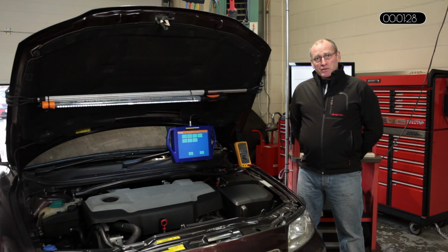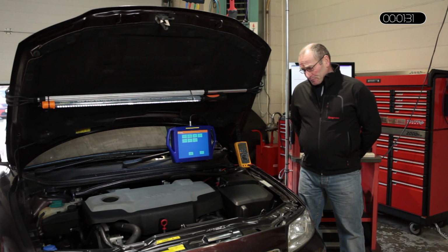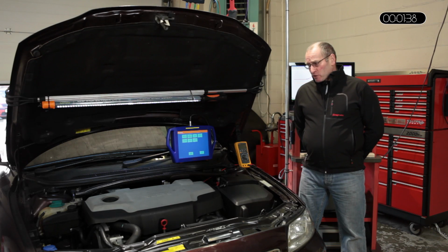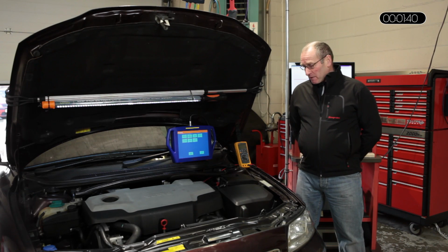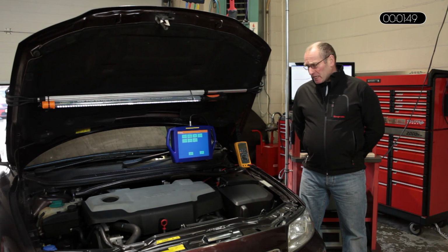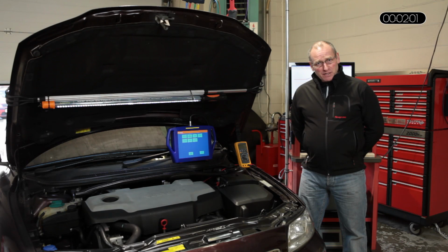This vehicle was presented with the usual range of DTCs, excessive soot mass content, relating to a blockage in the exhaust system, which can also be the catalyst as well as the DPF, of course. It was in limp-home, lacking power, and we began by examining the DTCs. It clearly demonstrated a potential DPF-related fault. It also had a DTC for glow plug error, and that was also dealt with as part of the repair process.